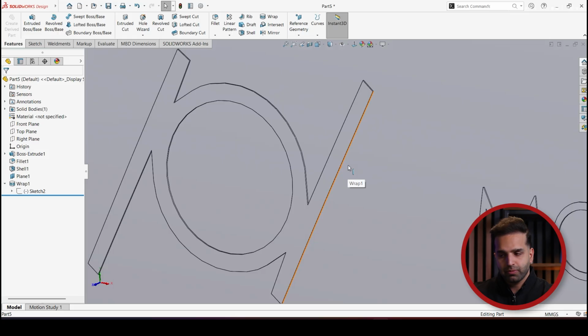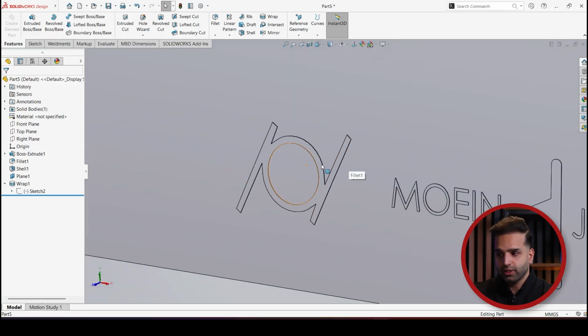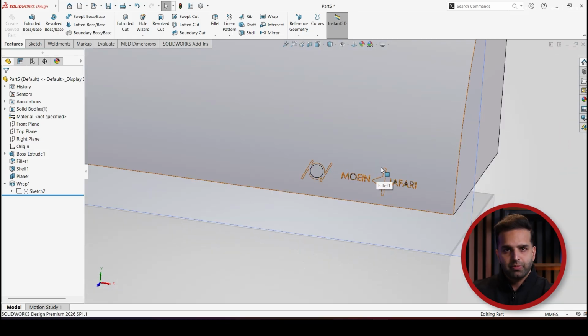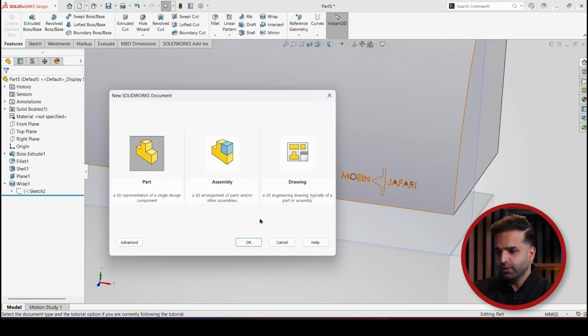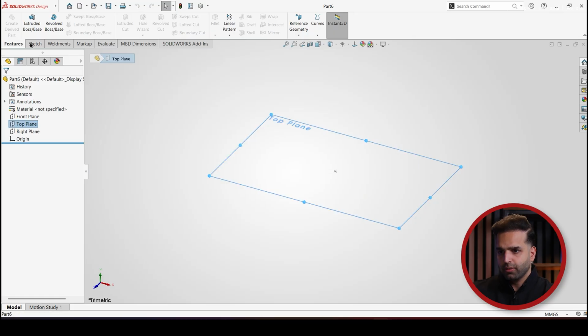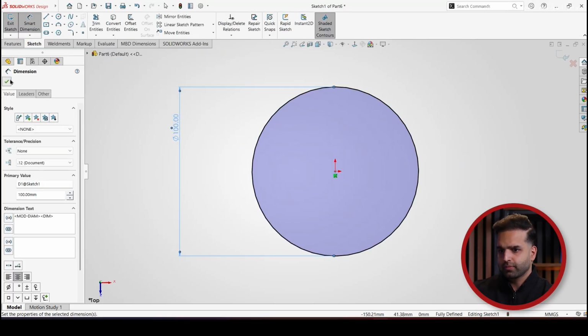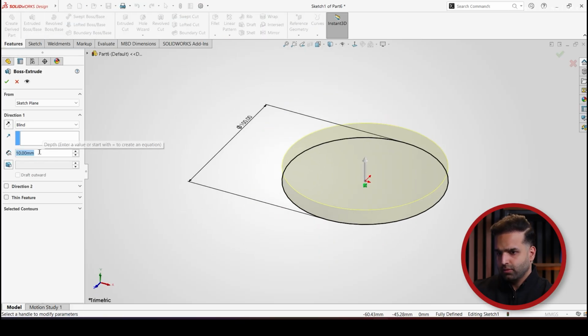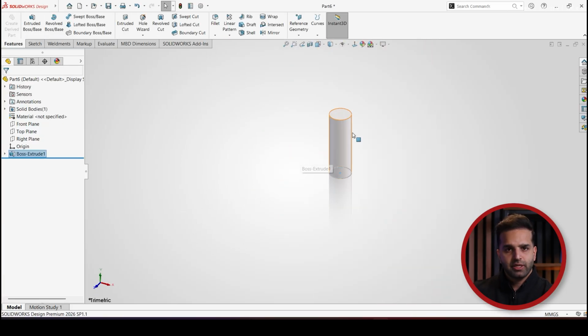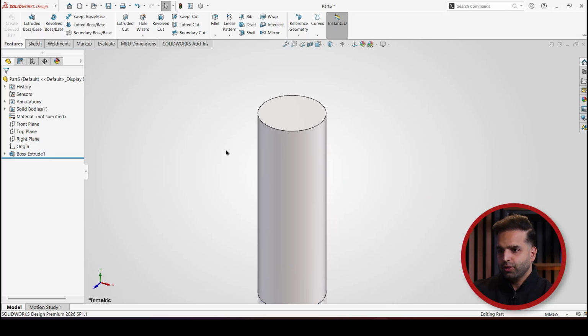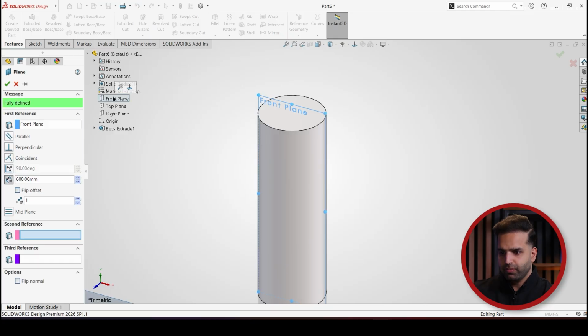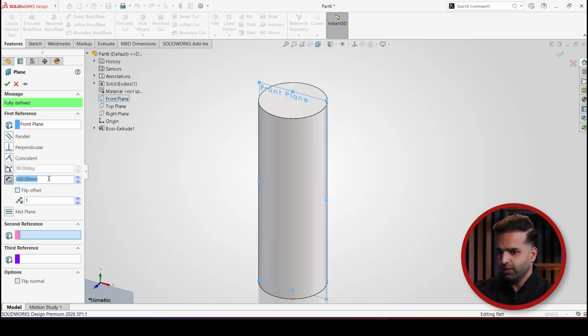This is how you can import the picture inside SolidWorks and generate this sketch. This is not the only gesture of the text on the body. For example, in the bottles, we can see the text all over them. So let's create another part, and I'm gonna create a cylinder. Now I wanna add a text all over this body. What I wanna do is to create a plane at a distance from, for example, the front plane, and its distance, maybe it is 70 millimeters.